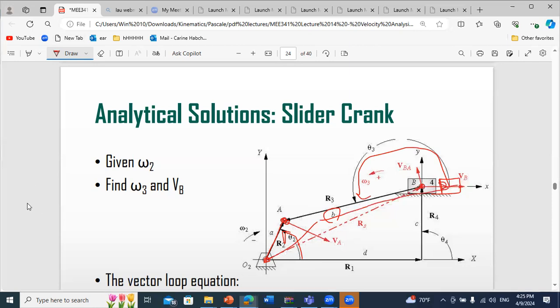However, if you take the third vector, we got it from the projection of the block position on the horizontal that is coming from the origin, which is pivot O2, okay? And because of this configuration, it's clear that as the block is moving, this distance is not changing.